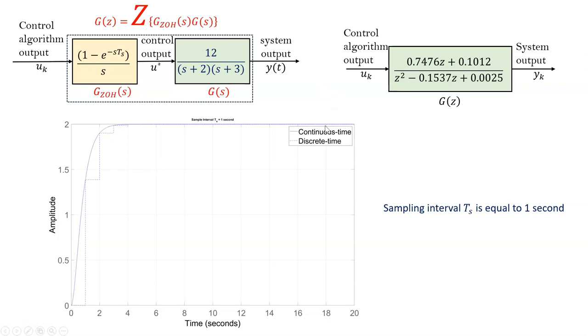In this video I'm going to show you how to discretize a continuous transfer function based on a sampling interval. Also how to check your partial fractions when you undertake the hand calculation. So here you can see on the left, this is your continuous system where you've got G, the transfer function for the zero-order hold, and also the transfer function G of s for your system.